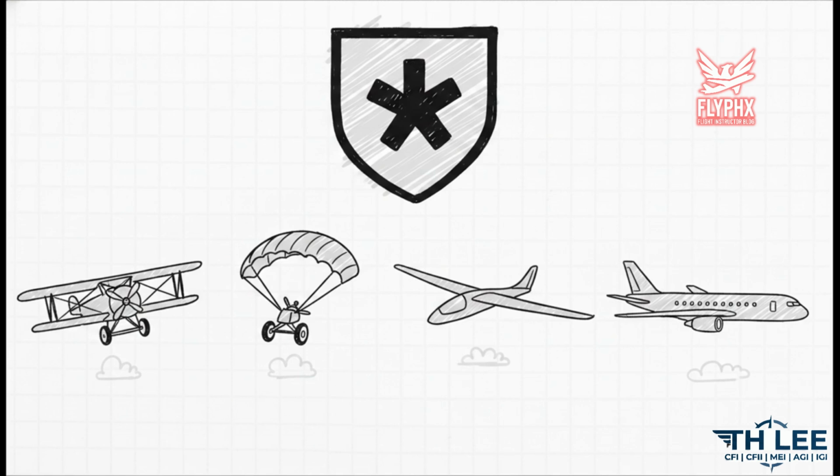Now, aviation obviously has a long, rich history, and the FAA accounts for that with some specific exceptions in Section 45.11. Aircraft manufactured before March 7, 1988, they can secure their ID plate at an accessible exterior or interior location near an entrance, but only provided the model designation and builder's serial number are still displayed on the exterior fuselage. Powered parachutes and weight shift control aircraft just need it on the exterior fuselage. Gliders, you'll note, are completely exempt from the standard exterior placement rules. Furthermore, if an aircraft is built for Part 121 operations, commuter ops, or for export, they're permitted to have the plate secured at an accessible location near an entrance. So it's not quite one size fits all, but the intent remains the same.